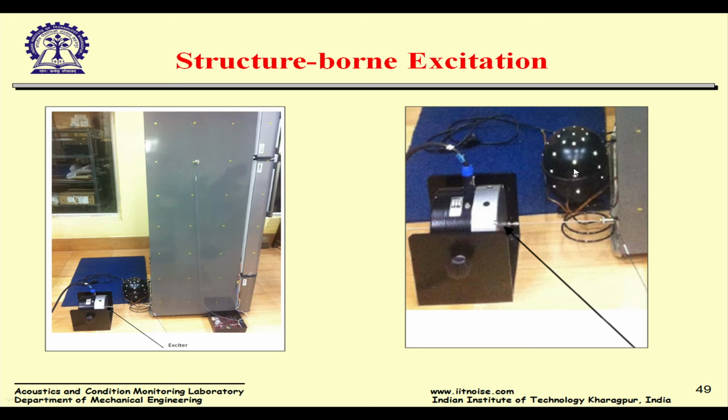We wanted to also see if the shell of the compressor was radiating any sound, so we wanted to measure the vibrations using a laser vibrometer. And also we did a numerical analysis using boundary element software, using this as a source, to find out what is the noise radiated because of the compressor shell. If anything could be done to the material of the shell, or to the mounting of the shell, so that the noise could be reduced.